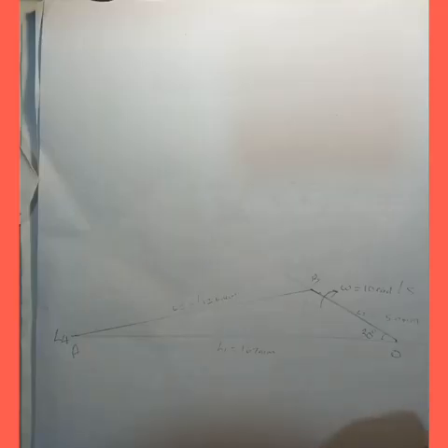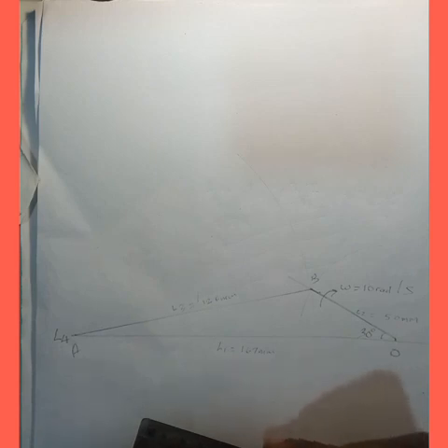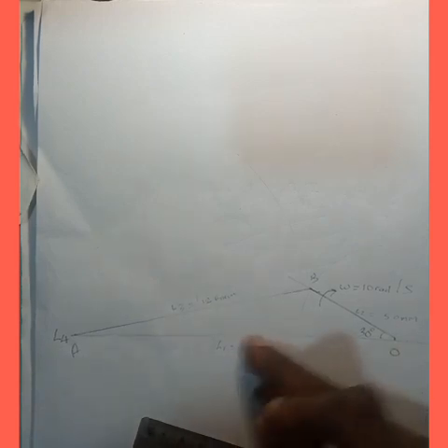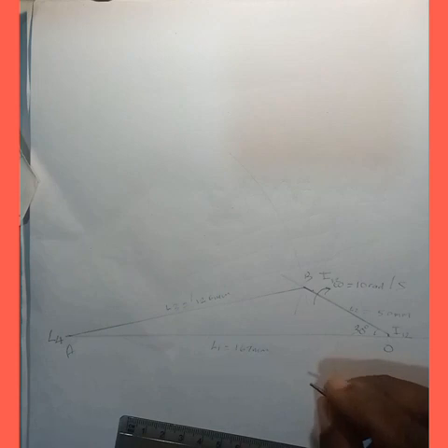So the next step is to locate the instantaneous centers you can observe on the slider crank mechanism. Here is link 1, here is link 2. In between link 1 and link 2, we have an instantaneous center of I12. In between link 2 and link 3, we have an instantaneous center of I23. Then in between link 3 and link 4, we have an instantaneous center of I34 here.